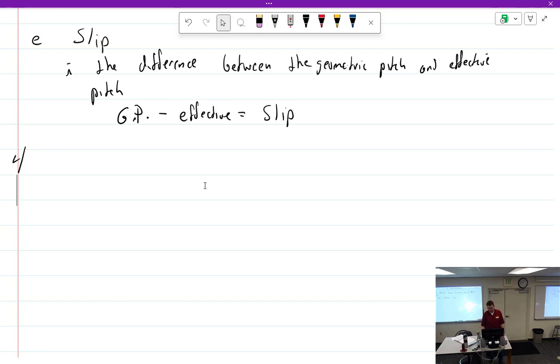What happened? It overshot the red line because the governor is working. We'll talk about that. He has cold oil, so it takes a second. So the engine oversped, and then the governor caught up and brought it back. So don't do that.